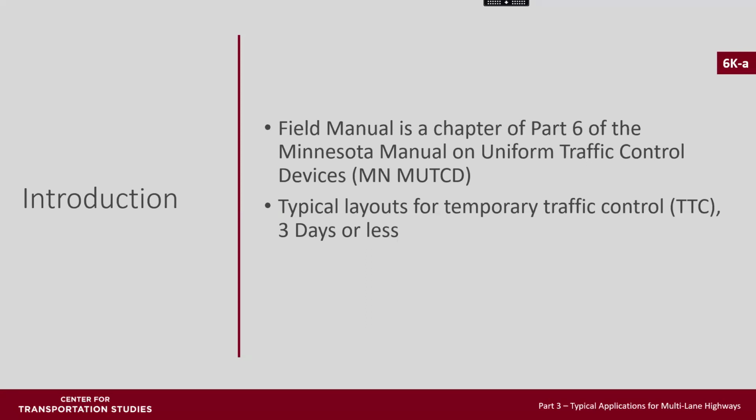It must be remembered that the goal of a temporary traffic control zone is to provide for safe and efficient movement of traffic around a location where the normal function of the roadway is temporarily suspended. To accomplish this, respect of the driver must be earned by appropriate and prudent use of traffic control devices. When work is not in progress or the hazard no longer exists, the temporary traffic control devices should be turned, covered, or removed from the area.